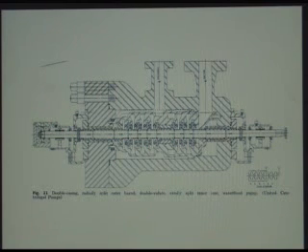The casing is the pressure containing part, and then you have a head that holds everything together and holds the axial thrust, and some very large bolts that hold this head in place because there's a tremendous force trying to blow the head off.